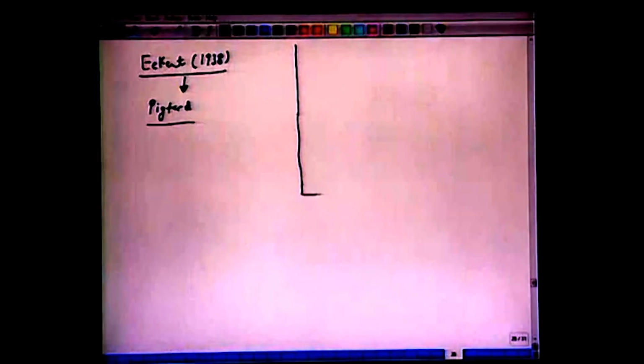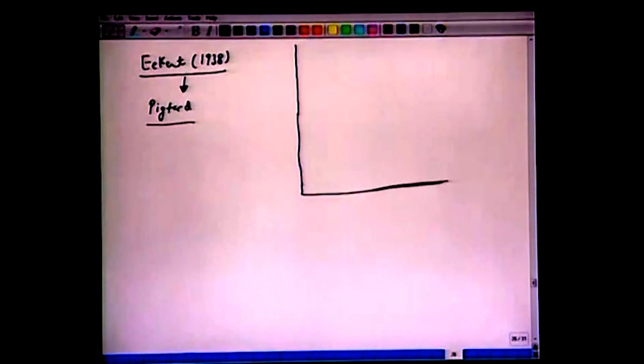This is a very old plot of 1938, and there have been several modifications or updates, maybe by Pickford later, to do some analysis for loading, flooding, and the pressure drop. It's recommended that you become familiar with this and solve at least a few problems, or address certain examples here.